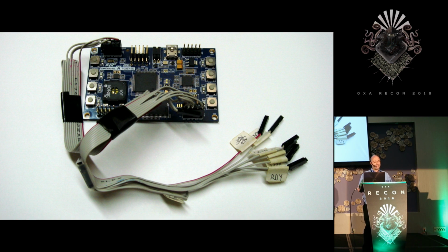At one point, I wrote software for an AVR32 device that has a synchronous serial peripheral that could handle the 27 megabit serial transport stream. My implementation was a little bit ugly, but rather than clean it up, I was able to use it as it was. It was limited to a 64 kilobyte chunk of replay and logging, which was good enough for what I needed to do. What it did show me is that the full transport stream passes through the ACP. There's selected programs that are decrypted.